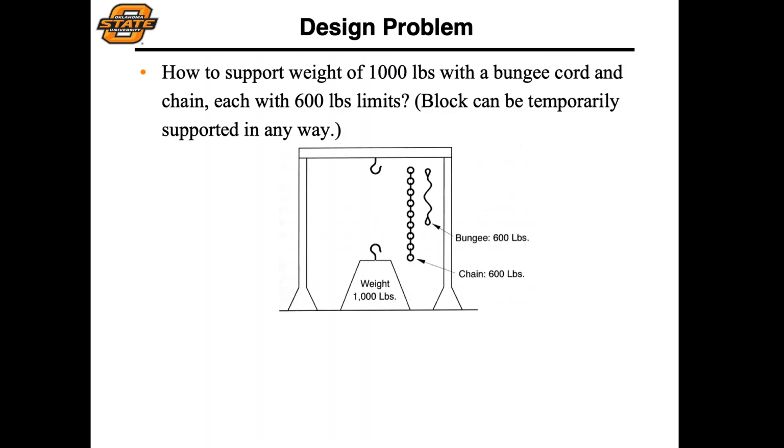So as an example, when we're designing an aircraft, we'll typically see, as we mentioned before, multiple load paths. One way to think about this is you might have an internal structure of your aircraft that's carrying part of the load, and you'll have that designed in a certain fashion with certain materials. And then you'll have a skin, which is also going to carry some of the load, but it's going to be fashioned in a different manner, and it may be manufactured out of other materials. So they're each going to have separate properties.